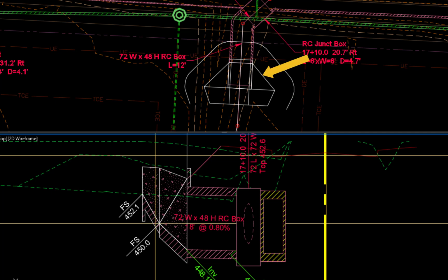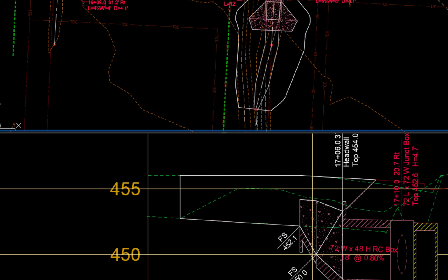In this section, the top of the slope paving is a straight line to where it joins the head wall. The height of the finished surface of the surrounding area varies between 2 to 2.5 feet above the slope paving. At a 3-to-1 slope, the horizontal distance of the surrounding earthen top of slope will vary from 6 to 7.5 feet from the edge of the concrete slope paving. A handrail will be installed along the top of the head wall and wing walls. Since riding lawnmowers can be operated on 3-to-1 slopes, earthen slopes should be 3-to-1 or flatter where possible.